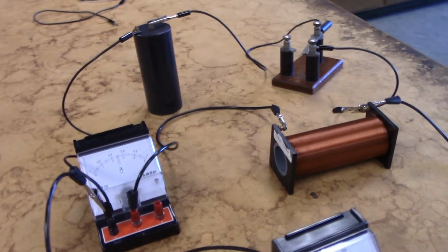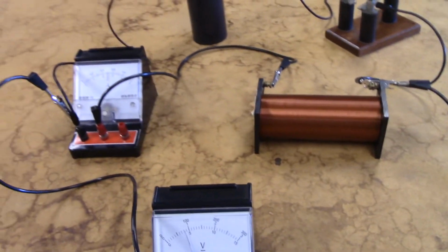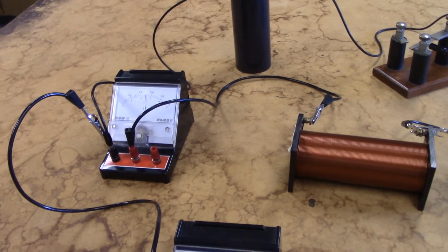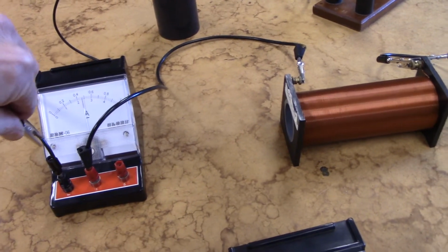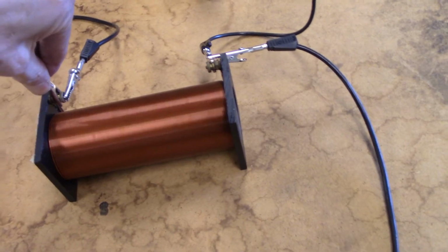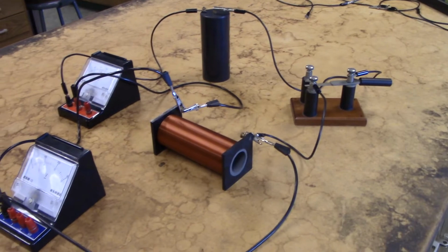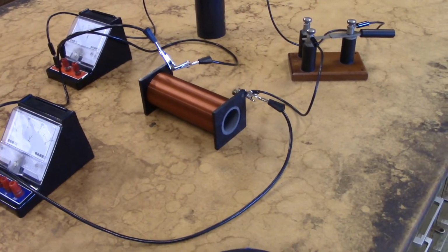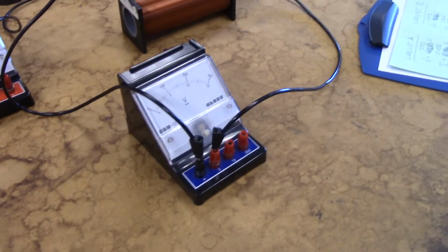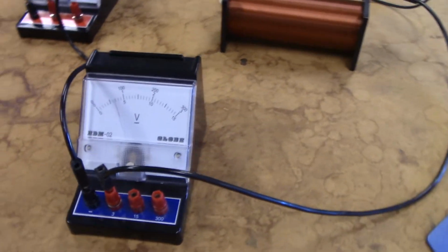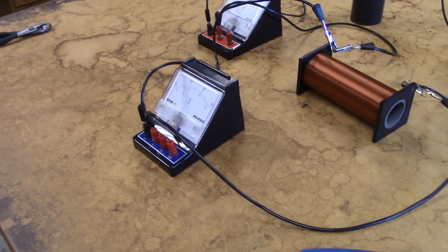Now, what we said was the voltage here is probably reading above and beyond what we want to include. So we're going to move the contact for the voltmeter closer into the coil. This should give us a better voltage measurement, but we're going to have problems with the current now. In any case, the voltage did really drop quite a bit. The voltage I ended up measuring here was 0.73, so it was a pretty significant drop.